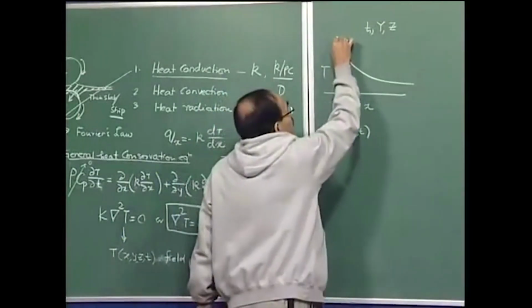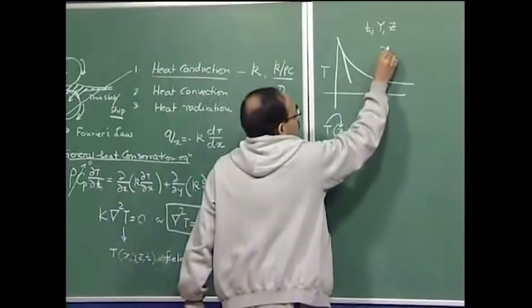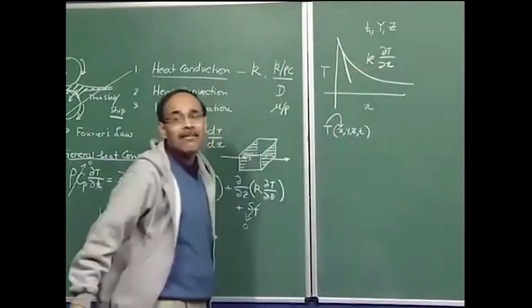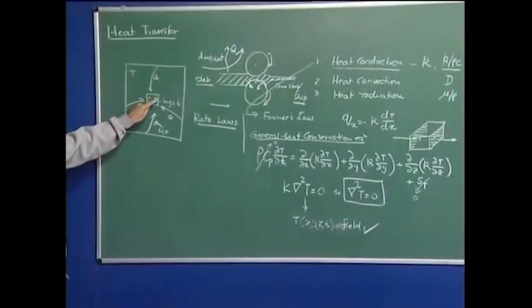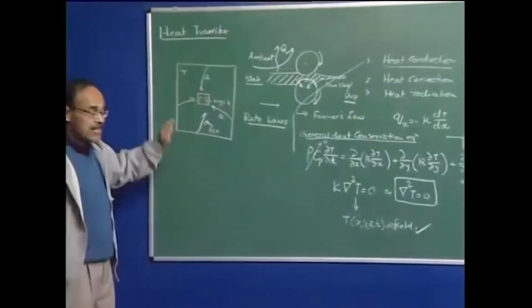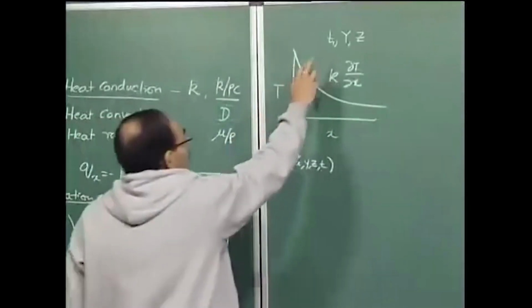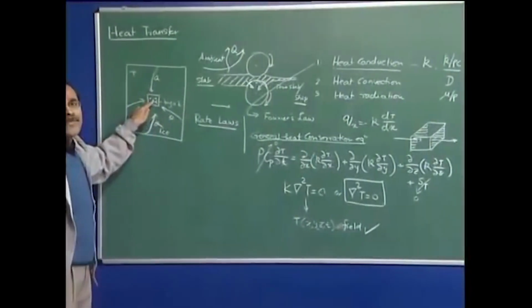And the slope of this line, which I can very easily determine, is a measure, and if I multiply this by the thermal conductivity it becomes the flux, and then I will know at what rate heat is really going from this point to this point. So, with the prediction of temperature, how can I find out the optimum reheat time?